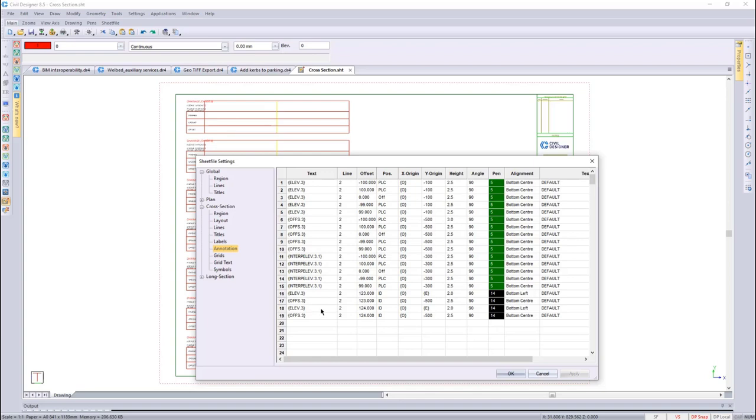I've added some additional entries over here, picking up elevations from my design layer. And I've used the code 123 for that parent string, front of curb. So it's elevation I'm picking up, and offset. The horizontal position would be directly below the position of that add-on string, the curb in this case, and then for the vertical position over here, I'm picking it up at the actual add-on string. The offset I'll put vertically at the actual offset line in the details section. So that's 50 millimeters below.